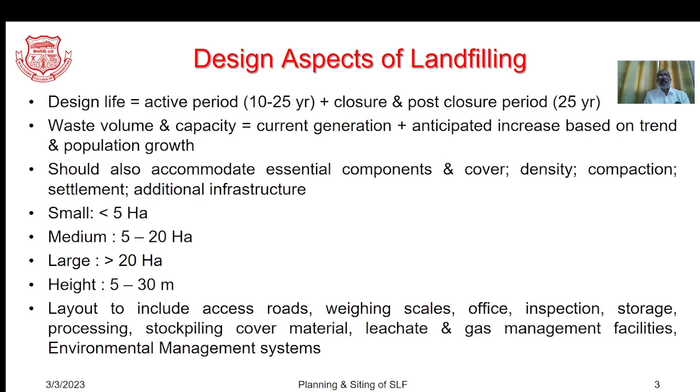So we can take into account these sanitary landfills in three forms: small, which has a requirement of less than 5 hectares, medium 5 to 20 hectares, and large more than 20 hectares. During the design stages, we can adopt the height in the various lifts as 5 to 30 meters. Additional features that we have to take into account are the access roads, weighing scales, certain offices, inspection mechanisms, storages, and similar aspects that have been included under this point.